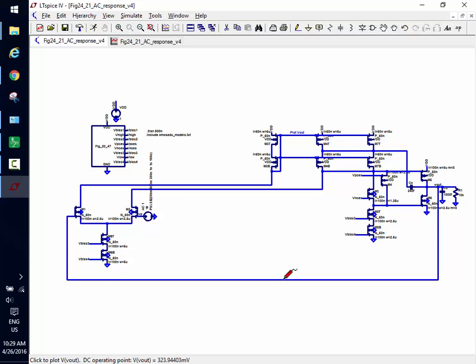I'm going to add a PMOS diff pair in there, and I'm going to sum the currents from the PMOS diff pair with the currents from the NMOS. And notice these are twice the size. Okay, I'm going to go ahead and now take my PMOS, I'm going to copy. I'm going to come over here, plop this down, and let's zoom in on here so it's not straining your eyes.